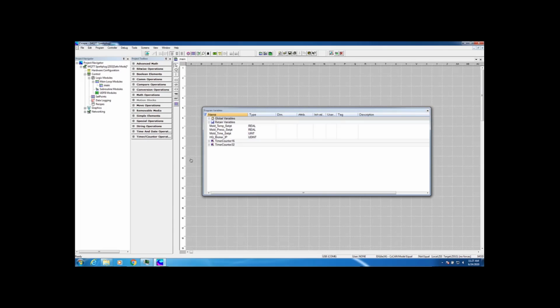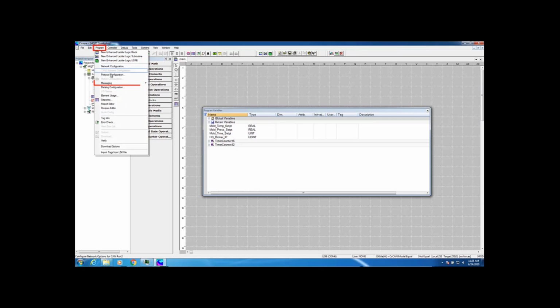For our last demo before moving on, I'm going to go through the configuration for MQTT Sparkplug, which is a new IIoT protocol which we've added in Service Pack 3. To configure MQTT, we need to go to the program menu in the top left of your screen, look down to messaging and then go across to MQTT.